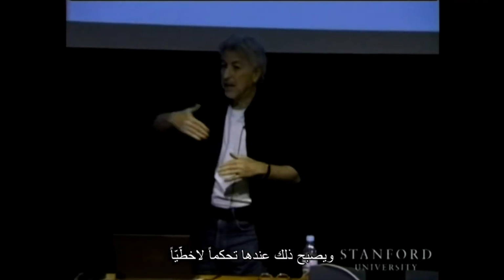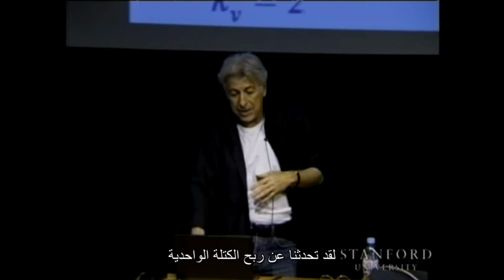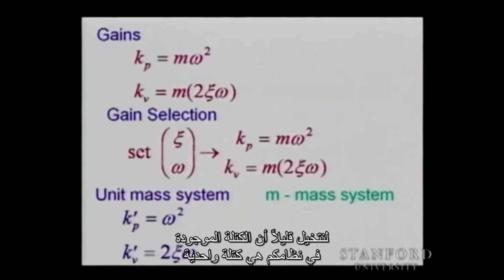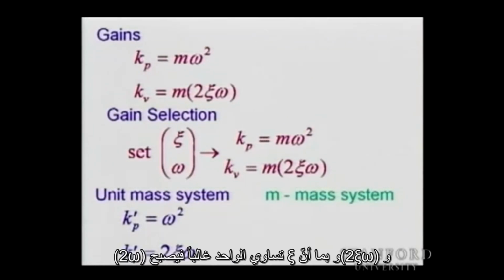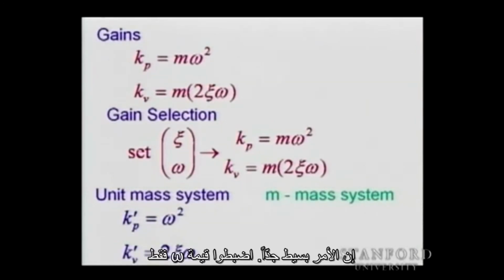And that becomes nonlinear control. So we talk about the unit mass gains. Let's just imagine that this mass was unit mass. Your gains will be simply omega square and 2 zeta omega, which for 1 would be 2 omega. Very simple. Just set omega and you get your Kp and Kv.